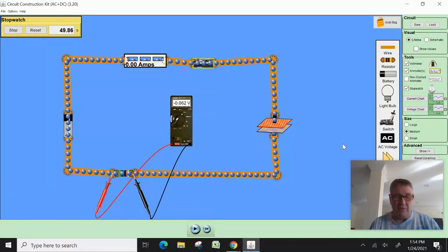But again, you should be able to go through this packet and understand what each of these circuits are going to do, both immediately after closing and after a long time. And if possible, I'd love it if you guys could build the circuits and actually test. Now, what I'm going to do in the next version, I'm going to replace this by putting a couple different resistors in here. That's going to raise the R, which is going to raise the RC, and you'll see it charges and discharges even slower. So remember, the RC controls the charging and discharging rate.